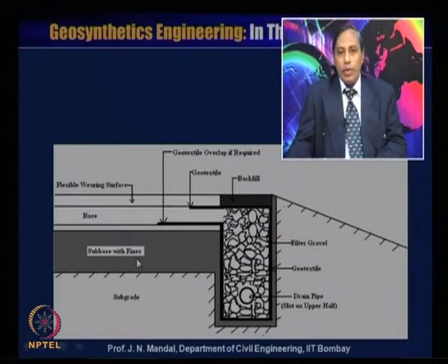Now, this is also a similar type. You can see there is a flexible wearing surface here, geotextile overlay if required, and this is the backfill, and this is the filter gravel material, this is the geotextile material, this is the drain pipe, and the slot is on the upper half, and this is the subgrade with the fines. So, when water percolates through this, you can also provide this kind of drainage system.